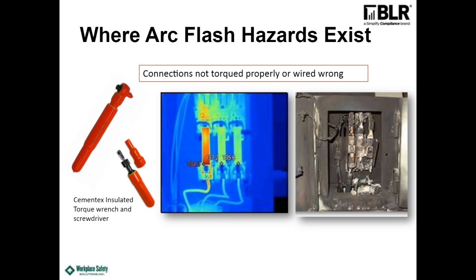I don't think you need to have an insulated tool because I personally would not torque anything in a live state. I would only do that in a de-energized state, and therefore I have torque wrenches and torque screwdrivers that are not insulated, and I never had to do anything with them in a live state. I've been an electrician for many years and never had to use an insulated tool for that. But all connections and all connectors should be torqued.